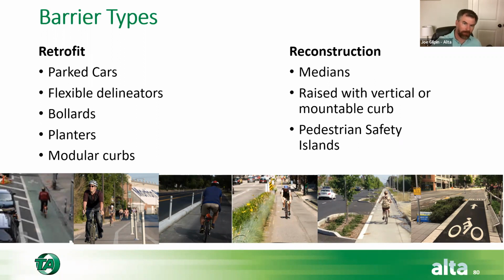All right, so with reconstructions, obviously we can do more. We can do integrally constructed medians. We can do things that are going to last without having to fix and replace flex posts, all those different types of things. So there is a lot more flexibility with how we can consider this. I've seen projects where we just literally go in and cut out from the asphalt that's there and pour in a concrete raised median or something like that. And that can be done potentially as part of a retrofit, not having to go all the way to a full reconstruction in that case. And anytime you can keep the drainage where it is, obviously a good idea.